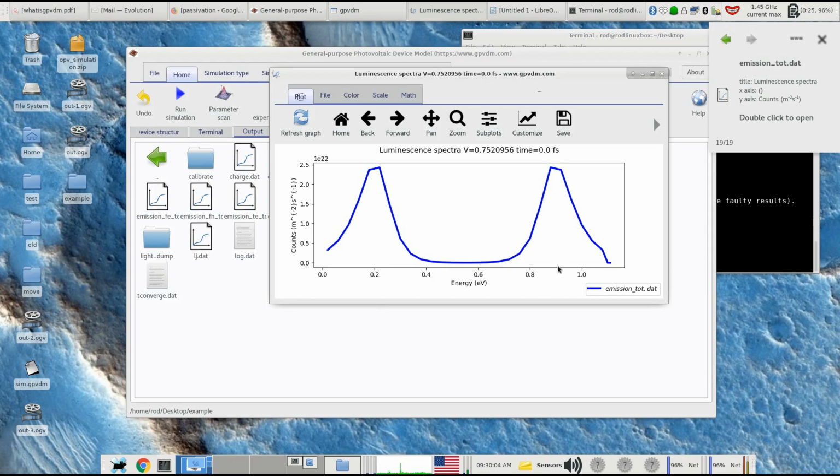This is, I guess, the wavelength you'd probably see devices emit at that have been pumped by a laser. And effectively, this shape is due to the shape the electrons and holes occupy in the density of states. And this is all caused by effectively free electrons recombining with trapped holes and free holes recombining with trapped electrons.